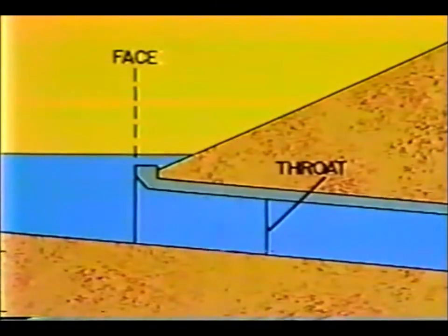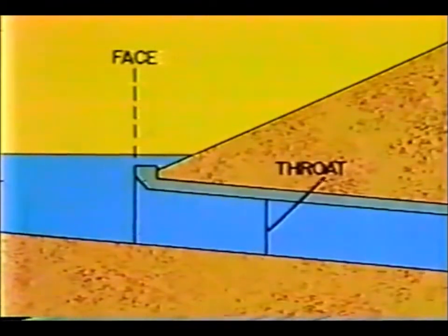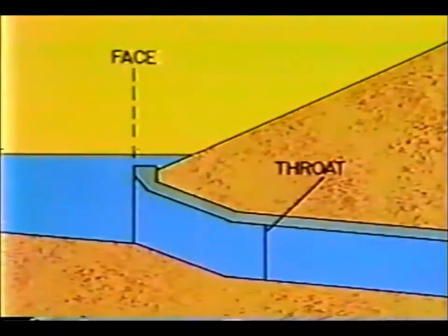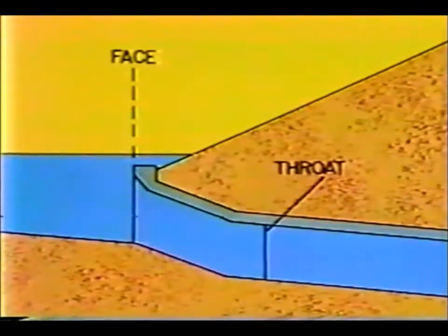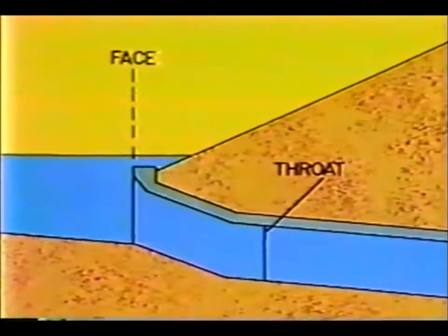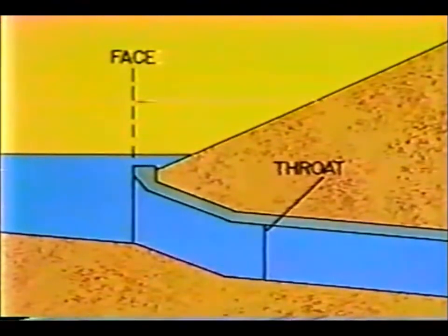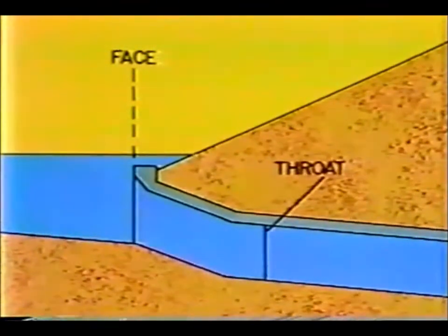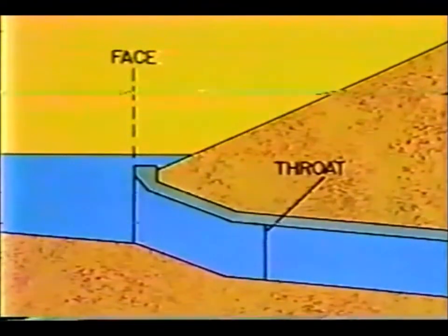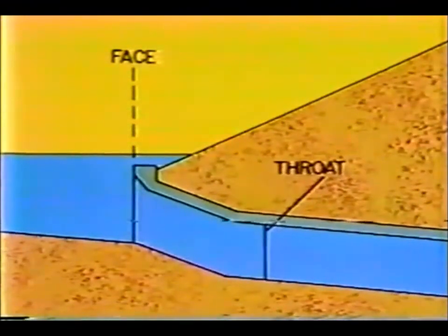The side tapered inlet reduces the culvert entrance contraction to a minimum. The only additional refinement that can be made is to depress the control section below the stream bed. This is accomplished by using the slope-tapered inlet. Lowering the control section provides more head above the control and increased culvert performance.